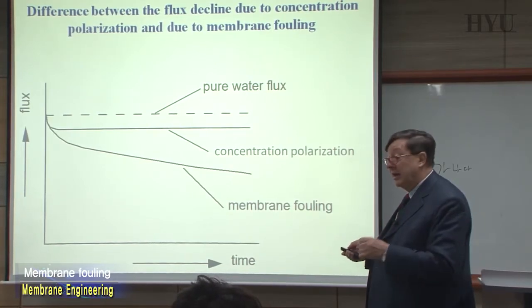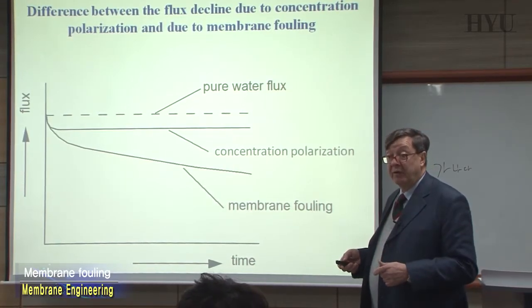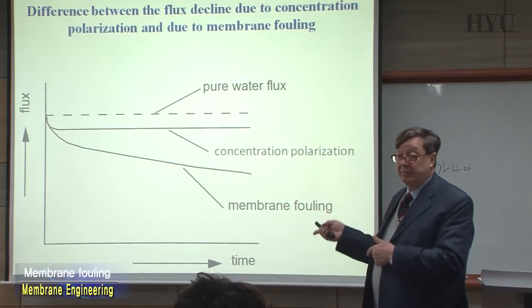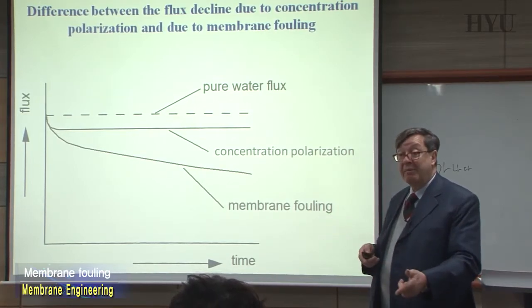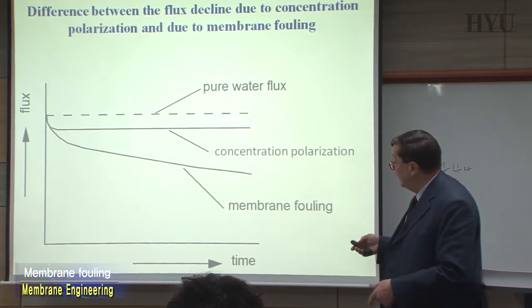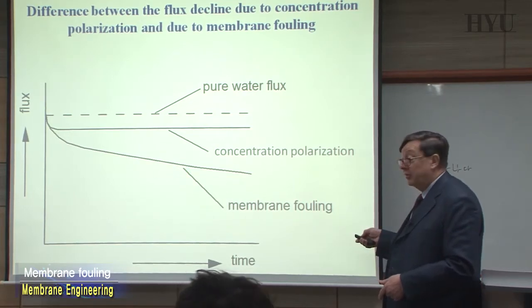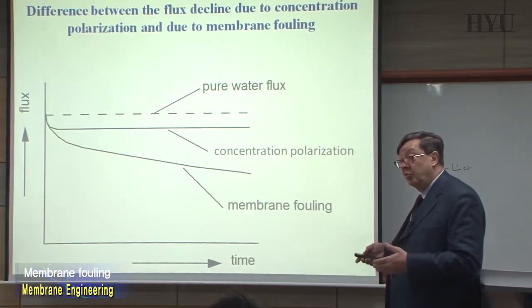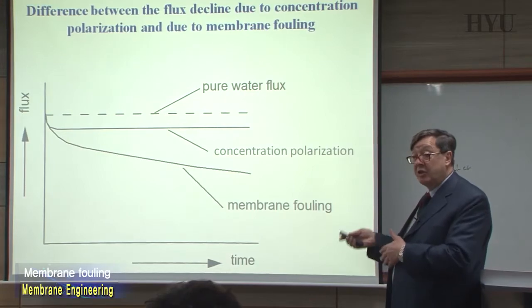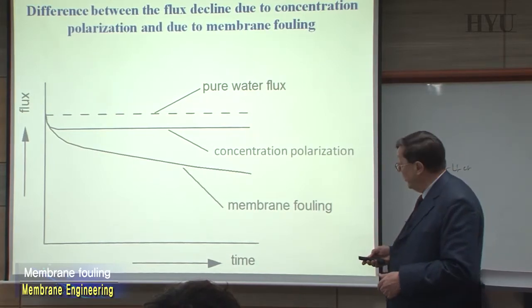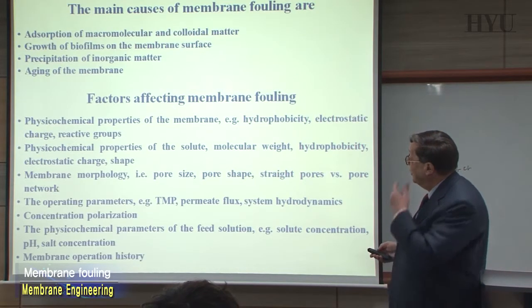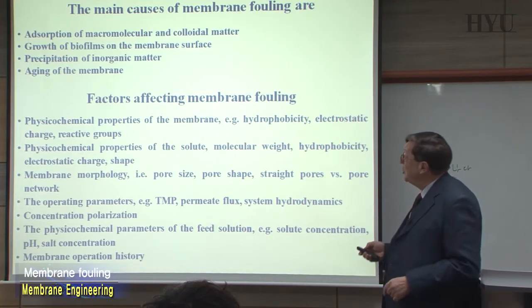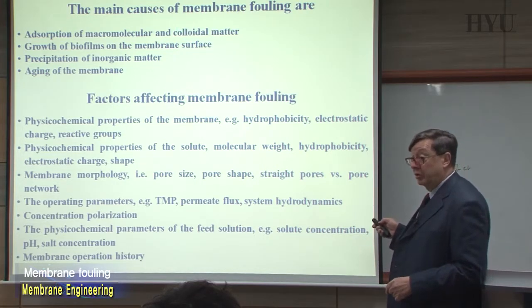This kind of fouling can just kill your membrane significantly. Lifetime, instead of being years, can become months or weeks, because this kind of deposit on your membrane surface can induce chemical transformation, pH changes, etc., etc. So we have to take care of the kind of phenomena. Now, which are the origin of the fouling?